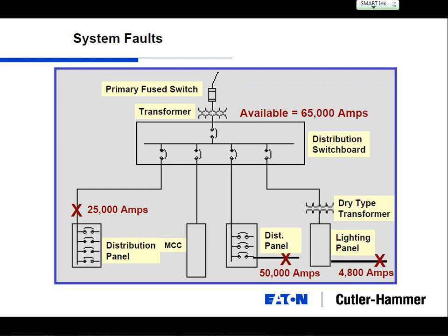If you're closer, maybe not 65 to 35, one of the options is to take cables and make a lap around the ceiling, for example. You're adding more cable. Each foot of cable is going to add a little more impedance. Each little bit more impedance is going to lower that fault current a little bit. It's one of those tricks you use when it's close.